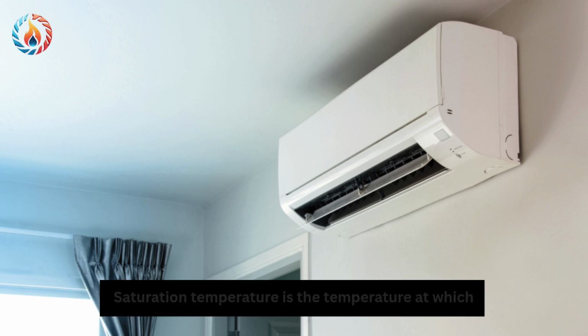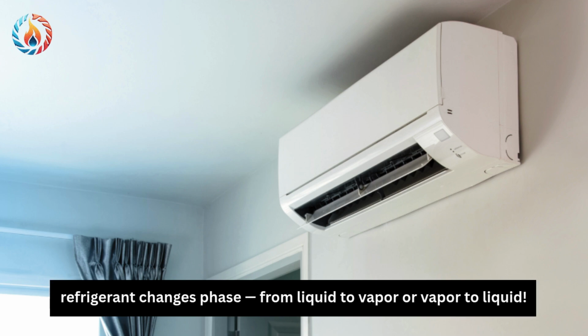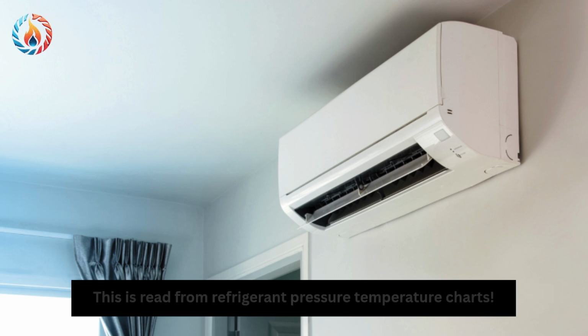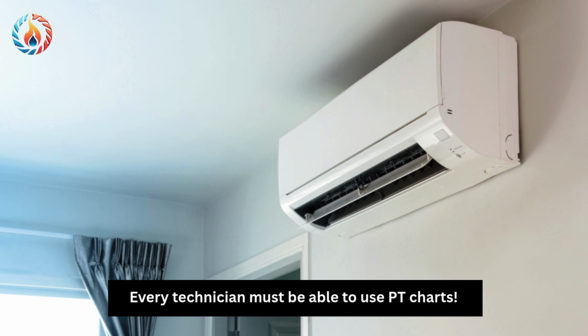Saturation temperature. Saturation temperature is the temperature at which refrigerant changes phase, from liquid to vapor or vapor to liquid. At any given pressure, refrigerant has a specific saturation temperature. This is read from refrigerant pressure temperature charts. Every technician must be able to use PT charts.